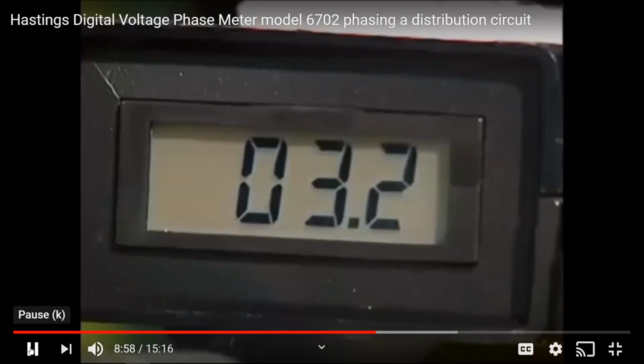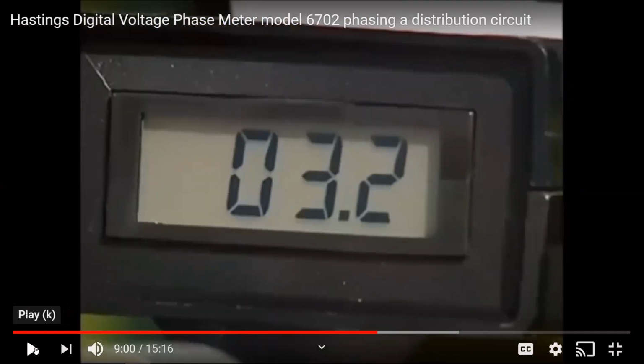I'm seeing 3.2. That's a bolted fault. The first cable he tested right here is reading a 3.2. What did he call it? Bolted fault. Now remember when he tested the sticks and went directly from phase to ground, from the energized side to ground, his reading was 3.2, right? Yeah, his reading was 3.2.